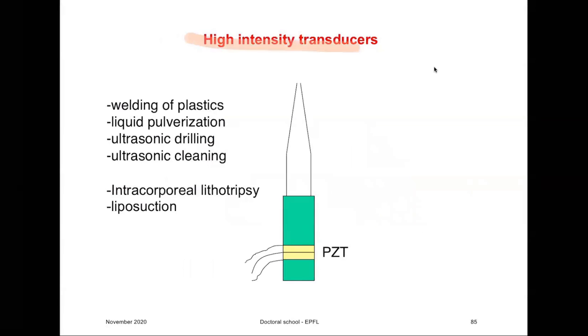Piezoelectrics are also used for high intensity transducers. Here you apply very large voltages on bulk PZT elements. You need a hard PZT because you don't want much electrical or mechanical losses. You are driving them at high frequencies in a kilohertz, sometimes even megahertz range. There will be also heating through domain wall motion, so you want to minimize that, and the hard PZT is the best.